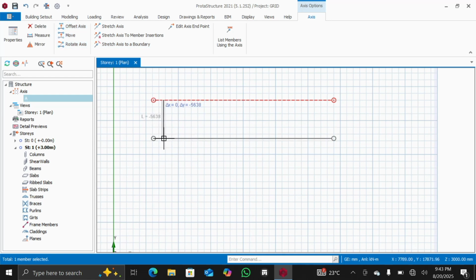What you're going to do, of course, is make sure from our grid A to grid B, it's about 5 meters, depending on what you want. You can make it 6 or make it 4, depending on what you're trying to design. When you come to your keyboard, depending on the keyboard you have, on some keyboards you long press Shift and then F2, on some it's Control F2. Personally, on my keyboard it is Fn, long press Fn and then F2.